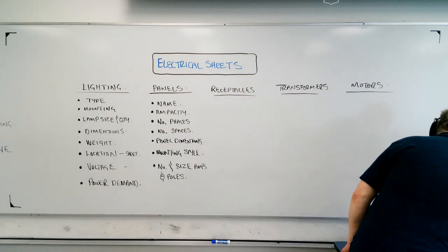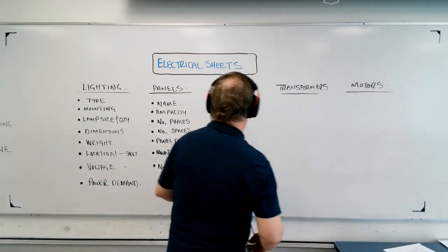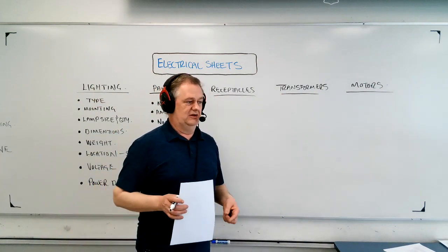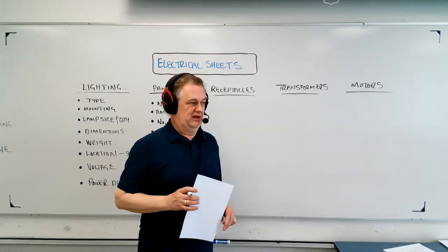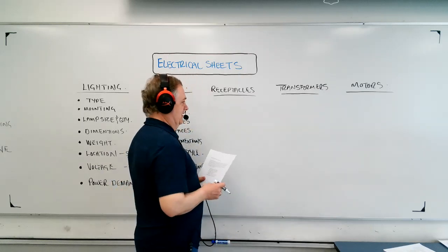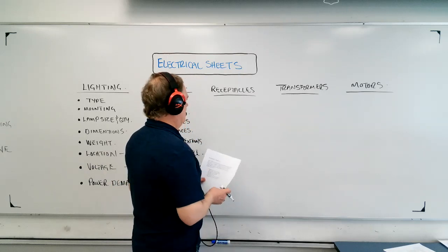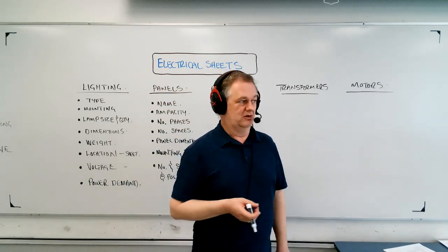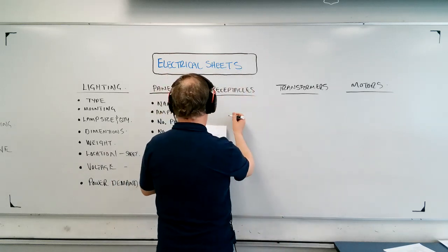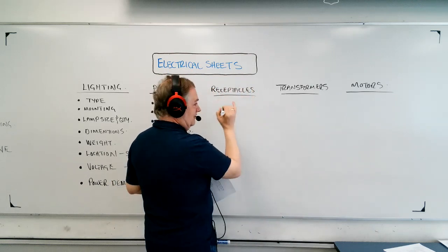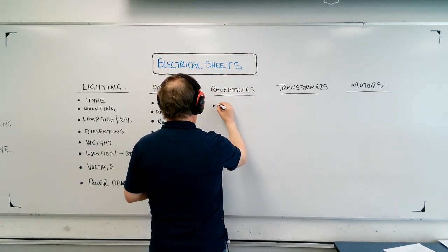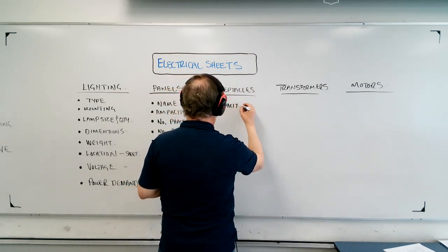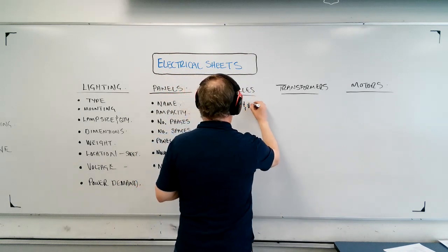Okay, receptacles, a little bit less. It depends entirely on the type of project. Particularly in, let's say, a small manufacturing facility that you're putting together, anything light, or if it's heavier industrial, you can have an immense amount of different power outlet receptacles in different locations. If you have a schedule of that, then you can literally look at it and say, okay, what is the ampacity and voltage of the receptacles? Ampacity and voltage.